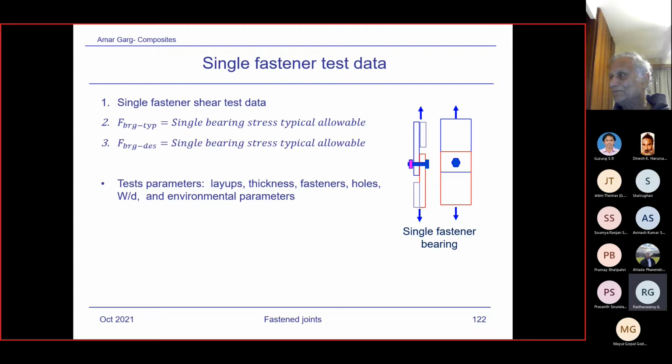Okay, sir. So in fact, quite often we had results from FEM on a spar or ribs where the stresses came out very high for the radius, and we had to increase the weight of those spars or the ribs. And physically we felt that somehow the results should not be that high.